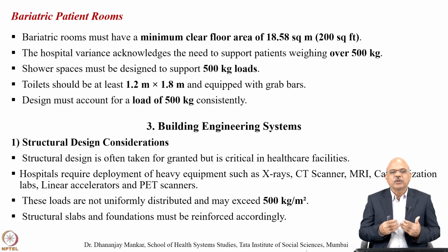Shower spaces must be designed to support 500 kg loads. With respect to injury to the patient, you need to design the toilet, which should be at least 1.2 meters by 1.8 meters and equipped with grab bars to hold the patient, so the patient can get support. The design must account for a load of 500 kg consistently, which is very important when you design such bariatric patient rooms.